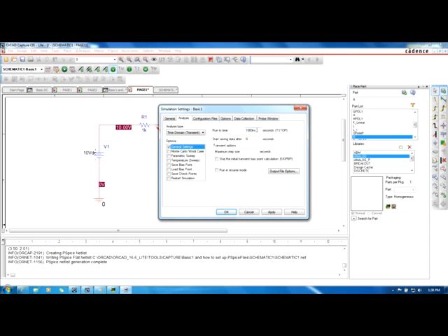Run time tells you how long the simulator is gonna run, how long it's gonna monitor voltage going through. In this case, 1,000 nanoseconds is more than we really need. Try to keep things working well. 1 nanosecond, how about that? Okay, then we have start saving data after a certain amount of time. Well, 0 seconds. We want to look at it immediately.